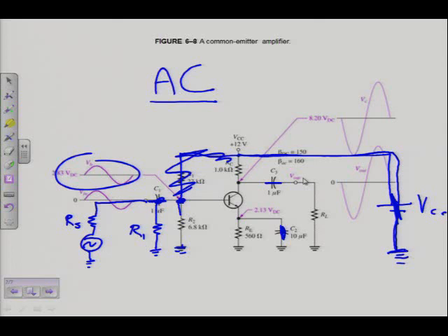So when you go to the lab and you are issued with all the components to build the circuit, and I can't remember what the signal gen, I think the signal gen there is a 50 ohm internal resistance, then please don't go to the lab technician and ask him, sir, I didn't get the 50 ohm resistor. Because you won't find it, no? It's the internal resistance of the source. Alright, but anyway, so we sorted out that part of the circuit.